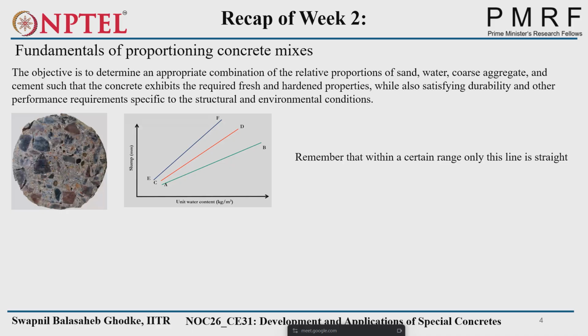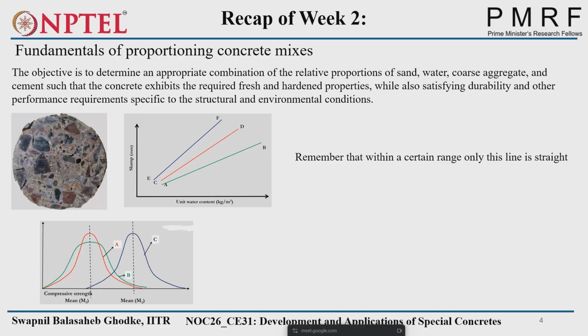But we have to remember why this line is not from the origin: this linear line will follow only a certain range. So how do we find it for your particular concrete mix? It depends upon the constituents of your mix and your water content. You have to find out this line. So you have to remember these things: slump is dependent on the unit water content.